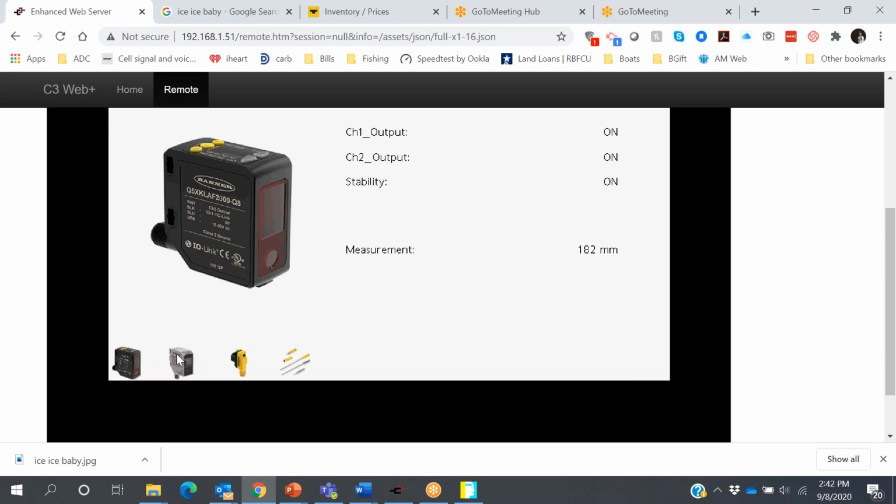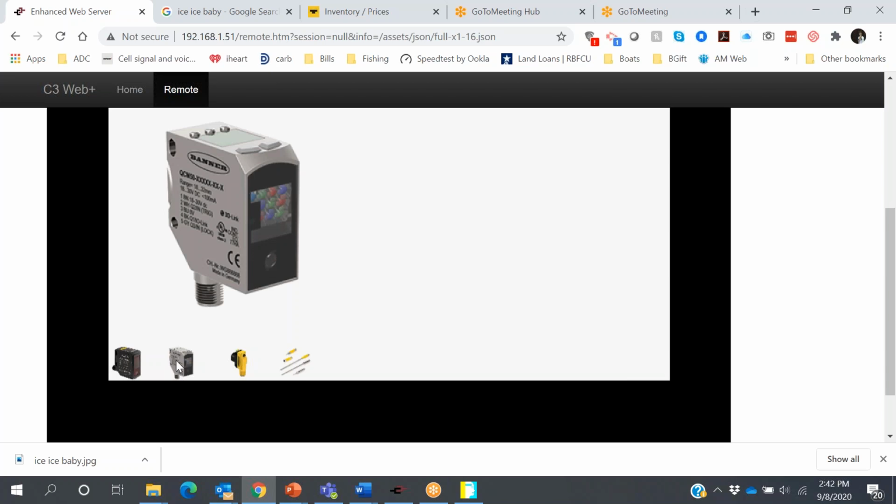We got our color sensor. So let's go look at our color sensor page. This is a true color sensor from Banner, and I've programmed 4 different colors into the sensor, and using the message we're getting over I/O link, again with that 3-wire cable, it should be orange there, absolutely. There's black, there is blue, and oops, I got to reteach, it looks like. I bumped it. There's our apple. Oh, there we go. Occasionally we're an apple.